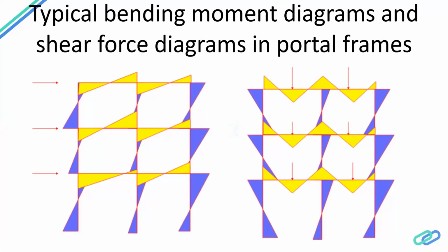So these were the few items I wanted to touch upon in terms of the bending moment and shear force diagrams. Obviously, this is not an all-exhaustive type of loading. For example, I just considered point loads as of now, but a structure would also see a bunch of uniformly distributed load, and that's what dead loads typically would be. They have a more or less similar type of behavior, but the only difference is that here we are seeing these discrete lines, whereas when you consider a uniform load, this will become more like nicely curved lines.